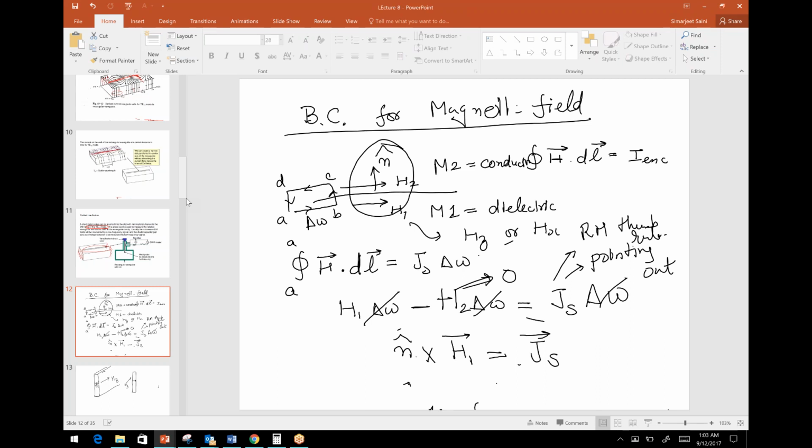You calculate the loss due to the electromagnetic field in the first run, and from that loss, because you have a finite resistance, you apply a small perturbation to the calculated electromagnetic field, and within 2 or 3 such iterations you are able to get to a decent solution.